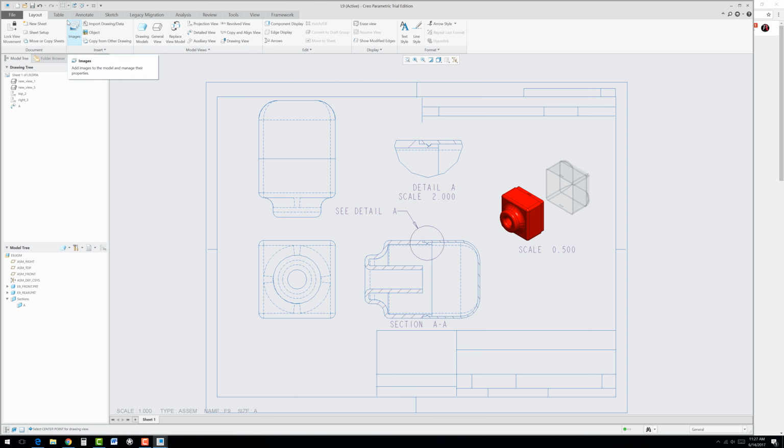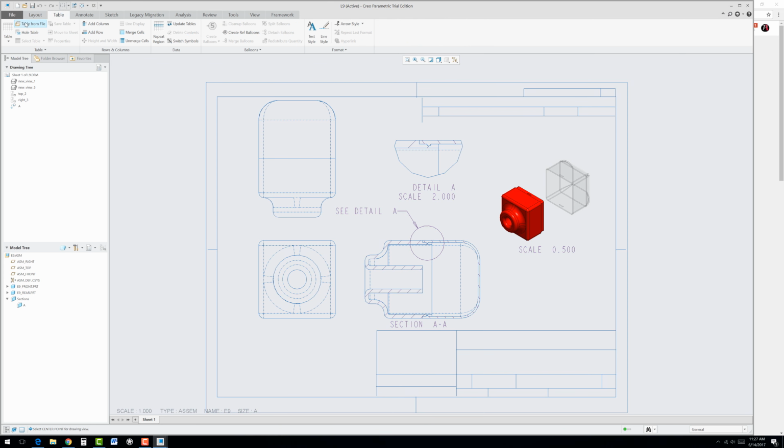You can actually go into Table, and especially with two parts, it's not terribly difficult. So here we could go ahead and click on Table, and we really just need a number, description, quantity, the labels at the top, and then the two parts that we have. So it'll be a total of 9 cells. Click, and now we can just drag it right over here. We'll leave it right there for right now. We'll go back and change the size in a moment.